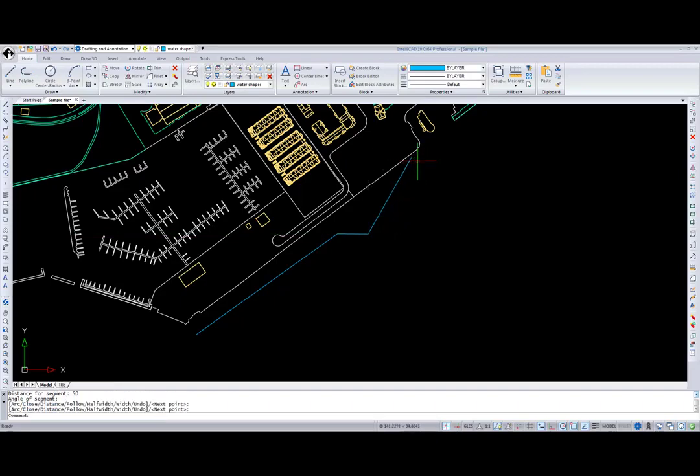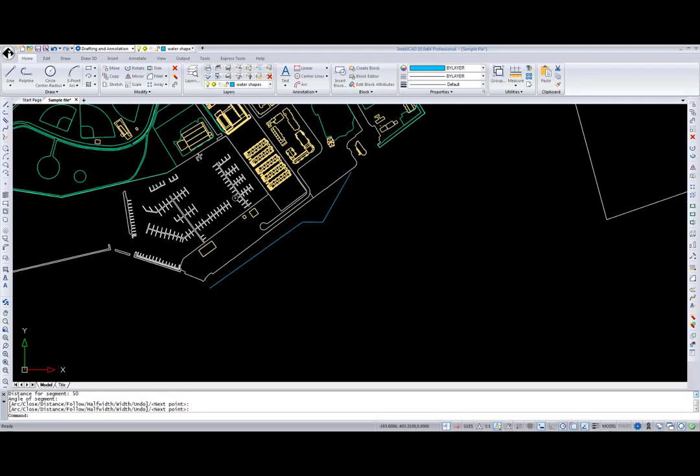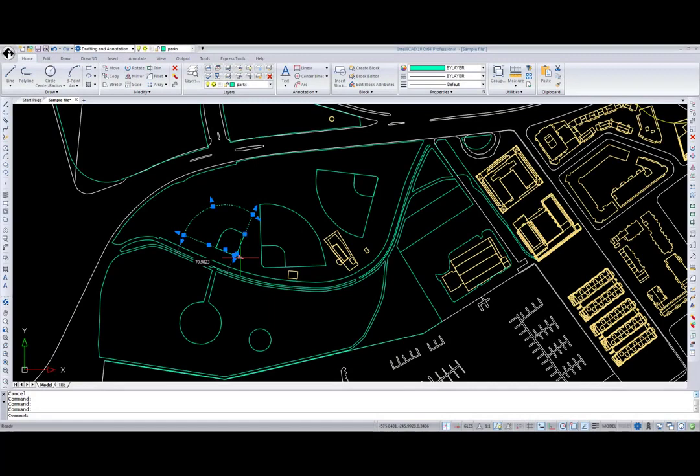Now when I finish my command, I want to use dynamic input to visualize dimensions of an entity. Select several entities, then float the cursor over a grip until it's hot to see the dynamic input dimensions. It's a really helpful and powerful feature. You can see the current dimensions without changing the entity or using different commands.